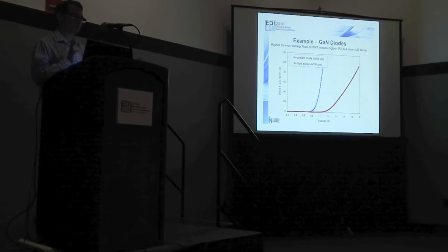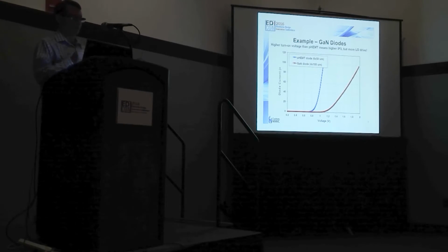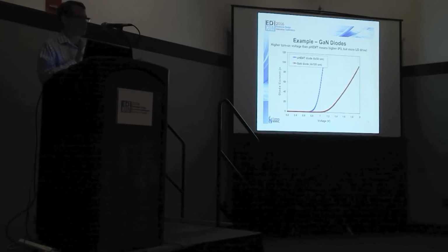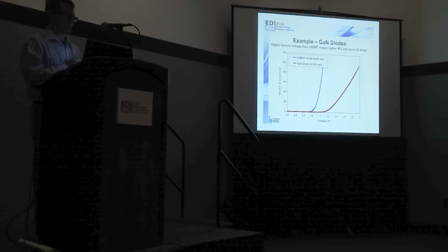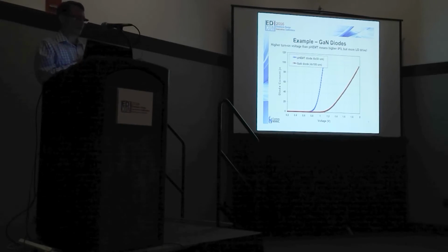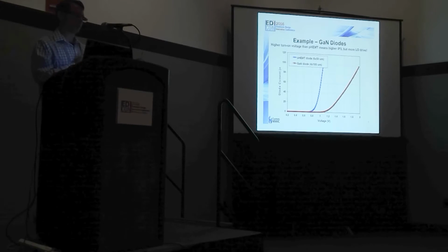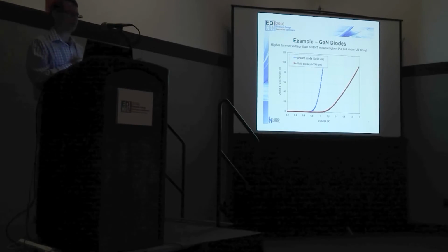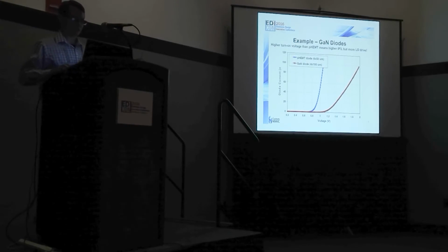So the diode, just from a physical perspective, looks a lot different. From an electrical perspective, there's some differences going on here. It's not just a slightly tuned GaAs diode. It is really its own unique element. And again, the higher turn-on voltage, we'll see, does lead to higher IP3, but it does also mean higher LO drive. So nothing is free, and certainly in gallium nitride, that is where we pay the price. It's the LO drive.